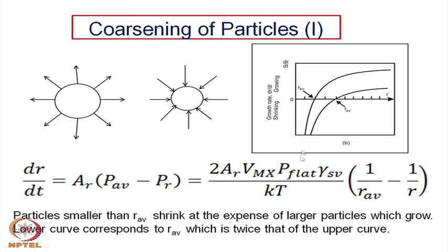That is also a phenomenon which happens in phase transformation like nucleation and growth, where there is always a critical embryo or critical nuclei size below which the nuclei dissolve, called the embryos, whereas above this critical size the nuclei grow and then the phase transformation takes place. So, that is a normal phenomenon in this kind of system.